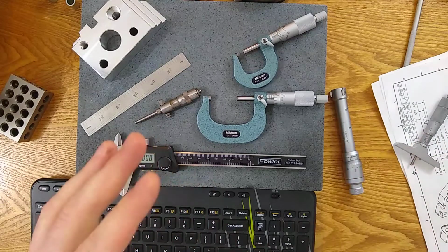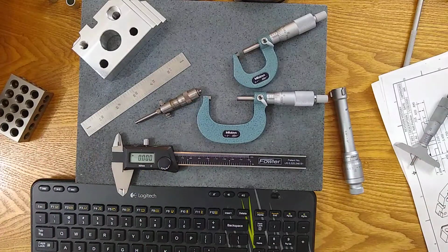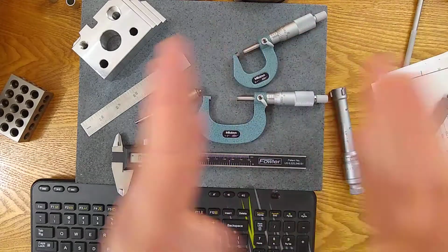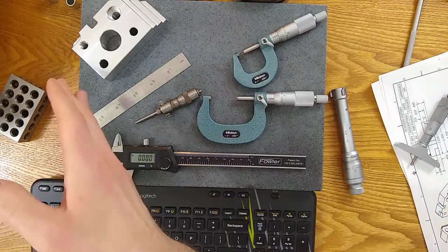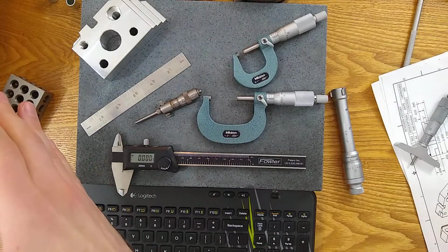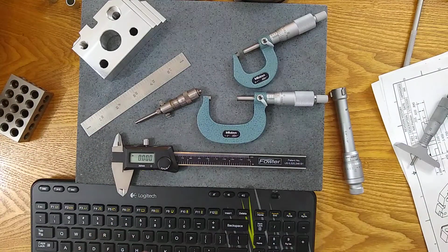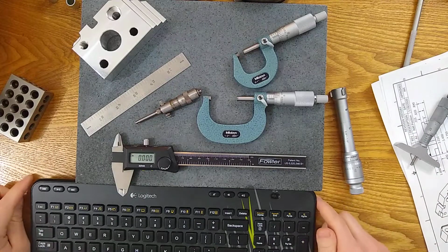And in fact, when I talked about gauge pins in the whole inspection video, I talked about how gauge pins are sorted. So all the ones that are bigger than nominal are in a set called the plus set. All the ones that are smaller than nominal are in another set called a minus set. So if you haven't seen that video, check it out where you can learn more about the gauge pins. And I will fix this slide.